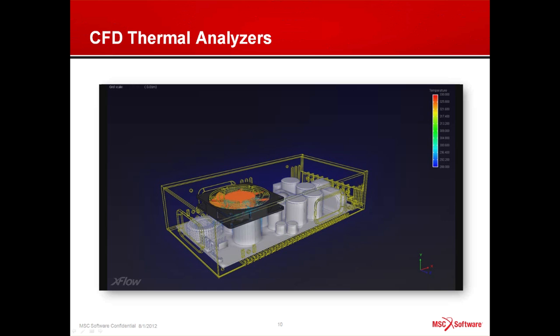If you have to add a heat pipe like they have on a laptop motherboard, they use heat pipes going from the CPU chip to the little finned heat exchanger, and trying to put that logic in, which is a one-way flow, and it's flow limited. Even if the delta T gets higher, it limits the Q through the tube. To put that logic in is pretty trivial in Sinda and generally not possible with CFD code.